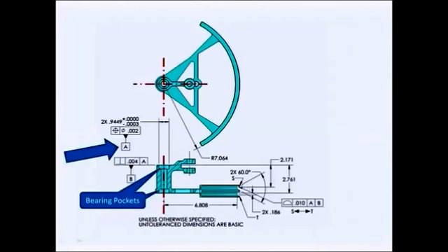On that critical radius and on these V-grooves, we have a profile tolerance of 10 thousandths. Now this 7.064 isn't directly toleranced, it's a basic dimension, which means that's the goal. And the tolerance of 10 thousandths is on this surface with respect to the axis established by A.